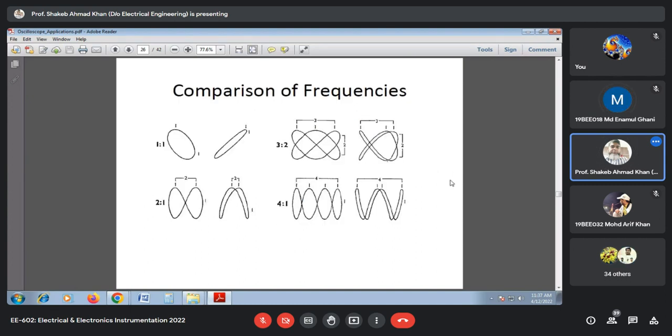Yes, sir. You see different types of Lissajous patterns are here. As I told you, when you have a circle or an ellipse, then it is 1:1, both the frequencies are the same. Now in this case, there are two horizontal tangencies and one vertical tangency, so it is 3:2. Two types of Lissajous patterns are shown here, 4:1, and so on. Many times you will find...